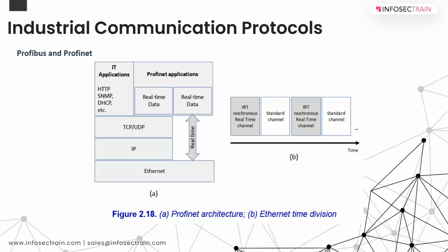Profinet is a standard that adopts Ethernet as a physical interface for connections rather than RS-485, and it has a token-based system to provide real-time functionality, modifying the protocol over a fraction of time with a given periodicity. With the remainder of the period, it operates in conventional 802.3 Ethernet.